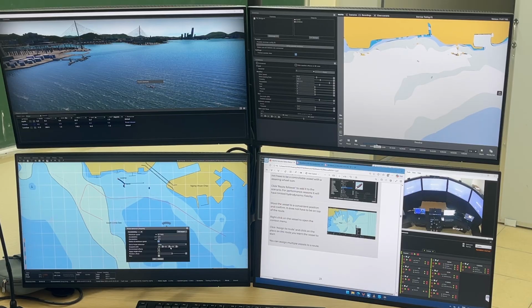You can also make it suspend. If you want, you can have it wait for like 5 minutes, and then after you press play and start the scenario, it will go and start. Then you can also disable the environment effects for the ship, and apply height offset. Not really used that often. Rotation offset as well. And over here you can run and pause it.